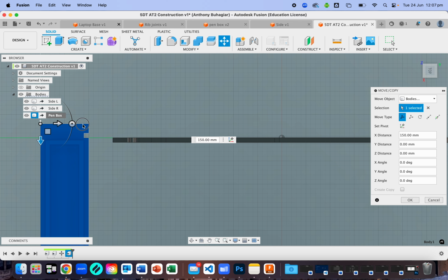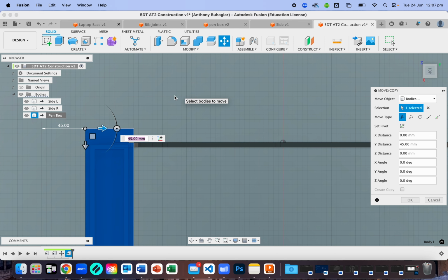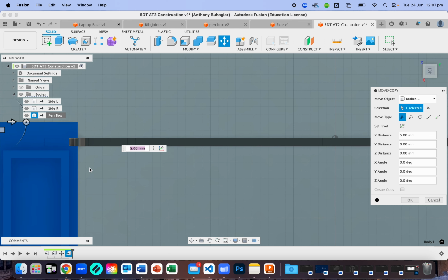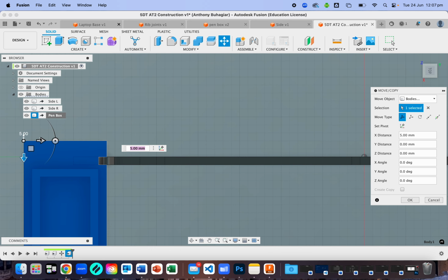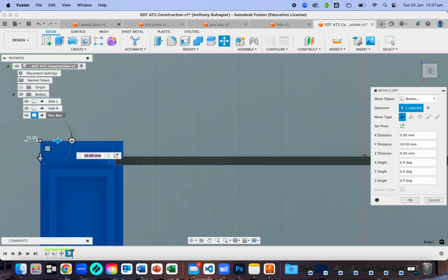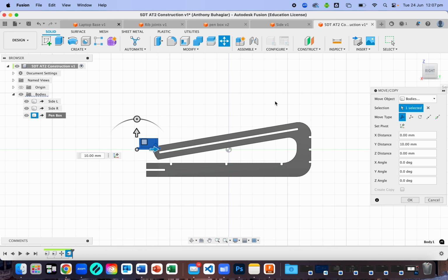Okay, and now I'm taking my time using the top view, using the side view to line it up correctly. And again, I'm doing this because I'm trying to simulate how I would put it together in the real world once all these pieces have been either 3D printed or laser cut. So I'm putting the product together virtually to troubleshoot if things don't align.